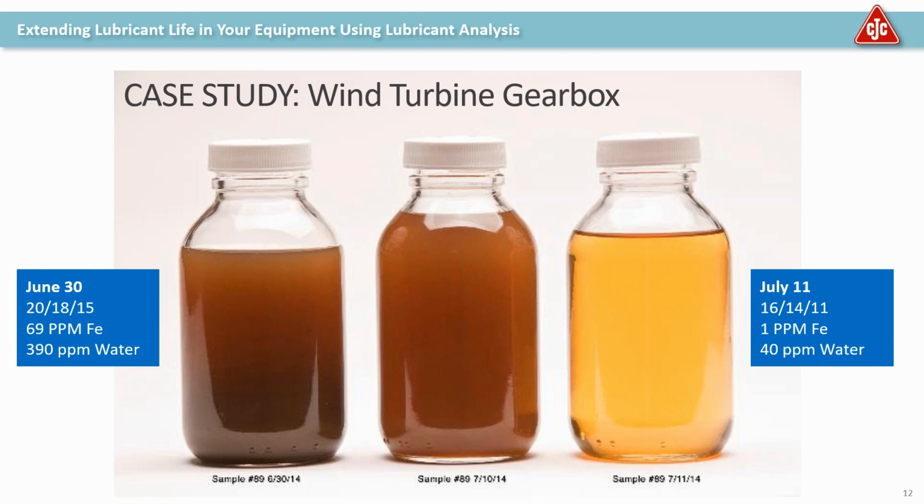At the end of June, it was upgraded with an offline filter, a fine filter. And you can see from June 30th to May 10th, there was significant progress. But then the decision was made, because of this middle sample and the analysis showing that there was still water, still some iron, they wanted to bring that down even further. So the filter insert was changed, and the very next day, the oil was sampled again. And you can see visually just what an improvement, getting down to 16, 11, the iron dropping to 1 ppm, and the water down to 40 parts per million.